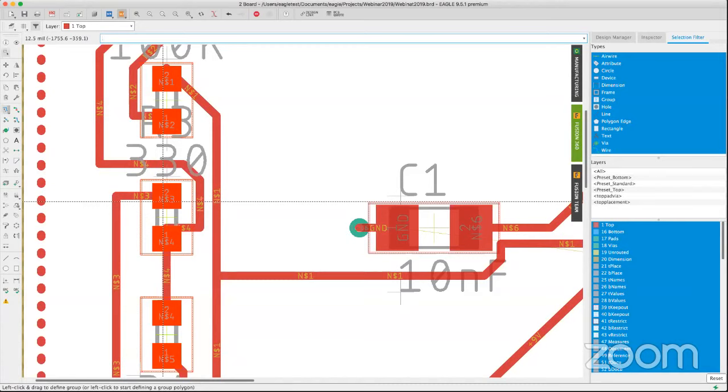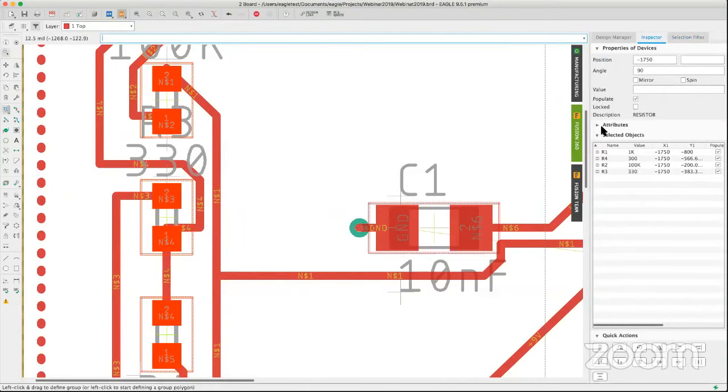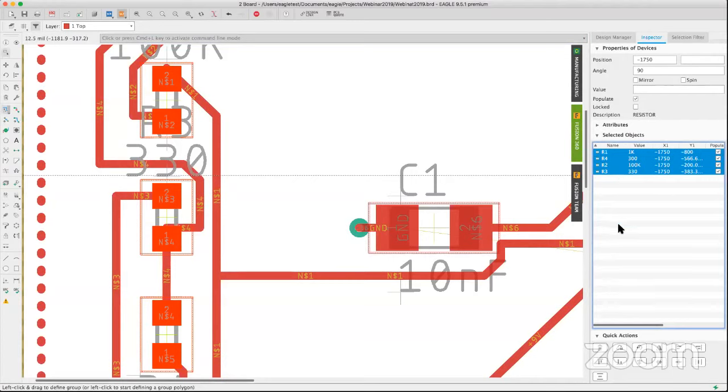There are other ways to do it. You could use something like the array tool. So component array under tools is one option. You can also use the inspector, form a group, and then with the inspector line them up and split them however you need to. So there's a few ways to do it. This is the align command, but this is the inspector over here, just to let you know. Okay, and then you have a little bit of control at this stage right here. Okay.